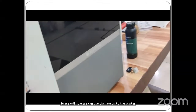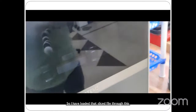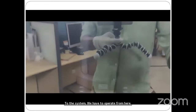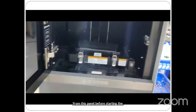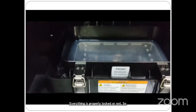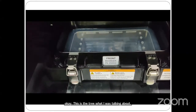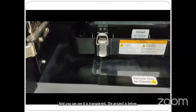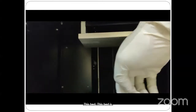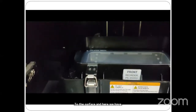So I have loaded that sliced file through this pen drive to the system, and we have to operate from here, from this panel. Before starting the print, let's check if we have missed anything or everything is properly locked or not. So the tray is okay. This is the tray that I was talking about, and you can see it is transparent. The projector is below, that is going to project the 2D cross section to here, and this bed is going to come down here to the surface, and here we have to fill the resin up to this minimum level.